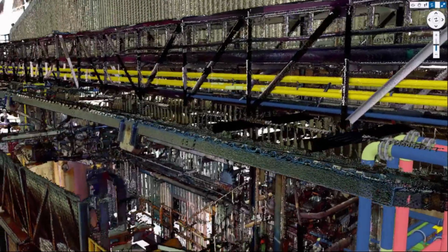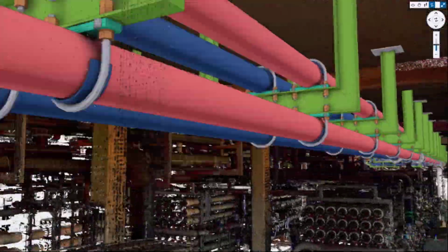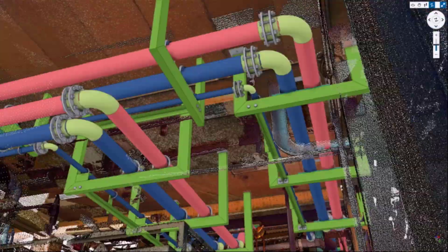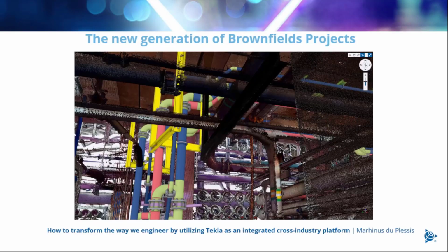So by fabricating elements off site, I'm sure you know, it saves us a lot of time in construction. So we are able to fabricate all of the structural supports and piping spools, deliver it on site, have the holes pre-drilled for the structural steel, and allows us to just bolt it in without having any issues going forwards.